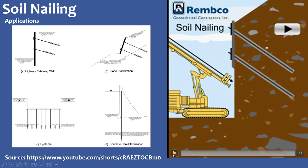Then we place a plate. Before placing the plate we had applied some shotcrete also. So you go step by step: first you excavate some area and nail the upper part. Then when the ground corresponding to that part becomes stabilized, you nail the lower part, and this is how you proceed in stabilizing the ground through nailing.